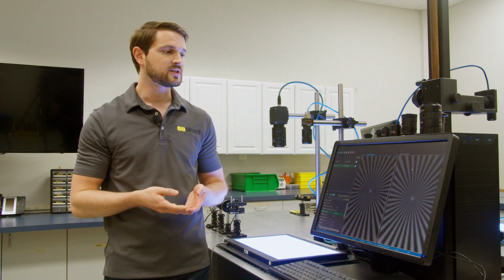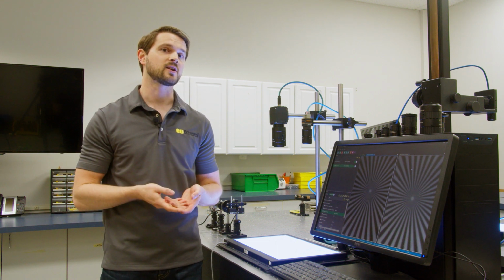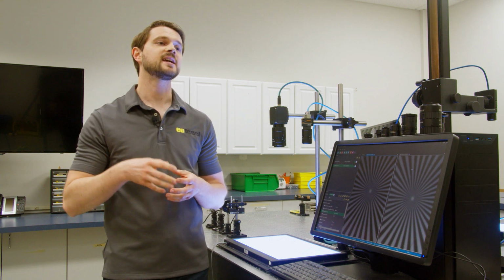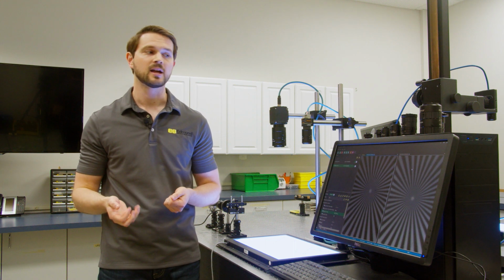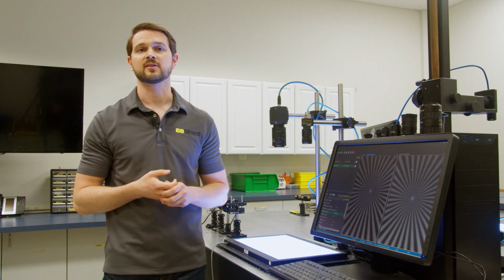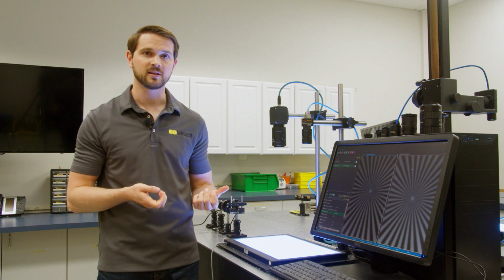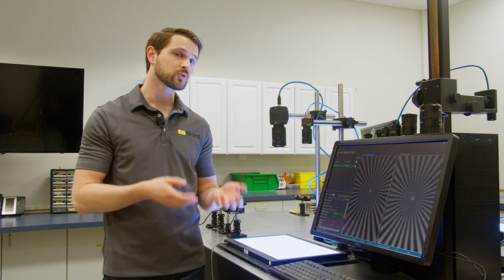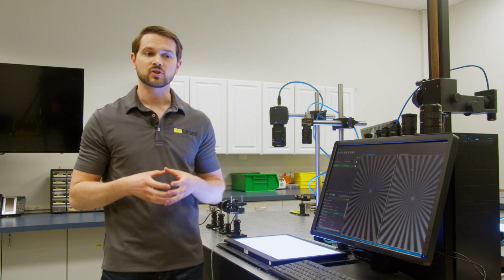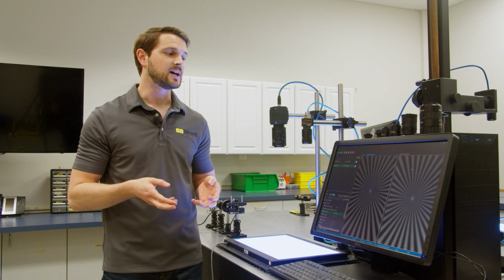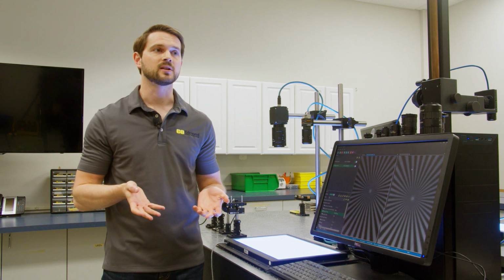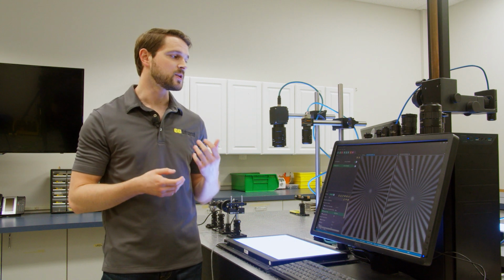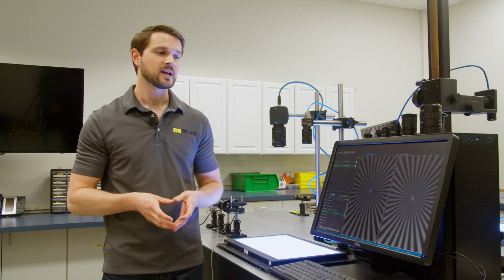This is something that's not often discussed: if you want to go to a higher megapixel count, blow up your image sensor. Generally speaking, if you blow up your image sensor, it tends to grow your pixel size as well. In this particular case, that's not happening, and in my opinion this is the better thing to do to maintain and actually improve your image quality, making sure your pixels stay as large as they can. When you go to really, really small pixels, you can encounter signal-to-noise ratio issues and other problems that you simply won't encounter with larger pixels.